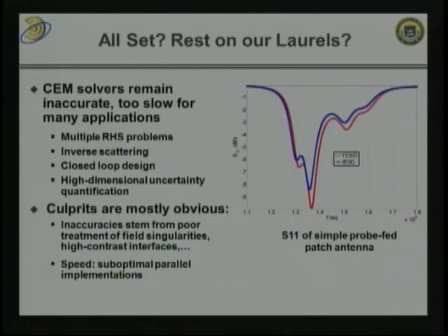Yes, there is some agreement between the results produced by these two solvers, but the agreement is by no means great, right? There are several reasons for that. One reason is that these commercial solvers do not yet have built in all the advances made in academia. Many of the things that I talked about here, the Calderon preconditioners and things like that, are not yet in these solvers, as far as I know. And this causes some of these problems.